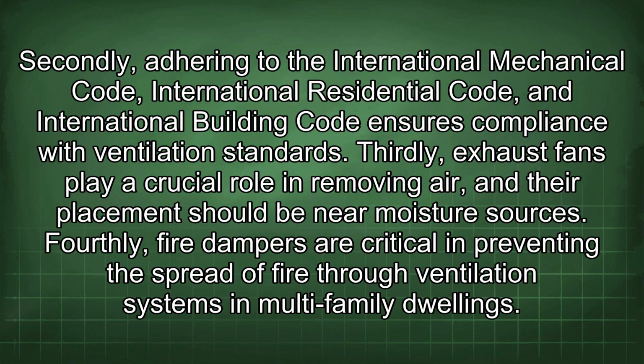Firstly, ventilation in bathrooms is essential to remove moisture, odors, and pollutants. Secondly, adhering to the International Mechanical Code, International Residential Code, and International Building Code ensures compliance with ventilation standards. Thirdly, exhaust fans play a crucial role in removing air, and their placement should be near moisture sources. Fourthly, fire dampers are critical in preventing the spread of fire through ventilation systems in multi-family dwellings.